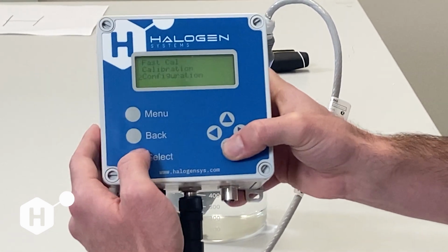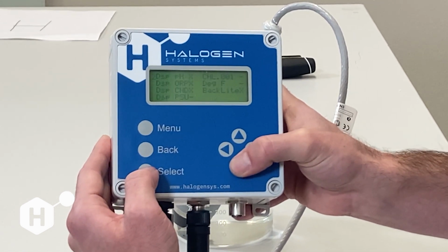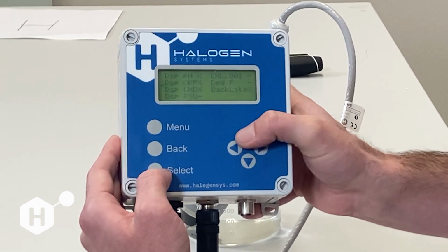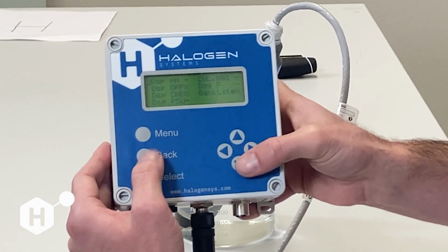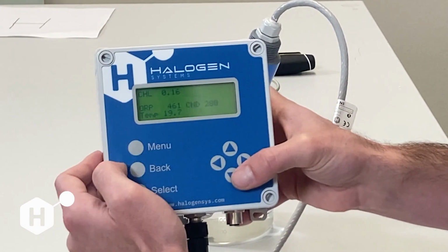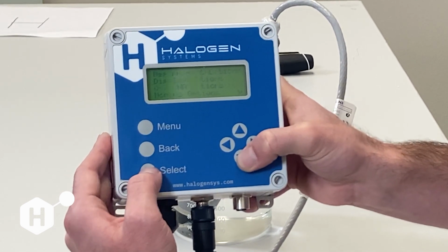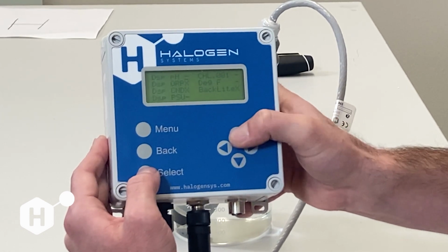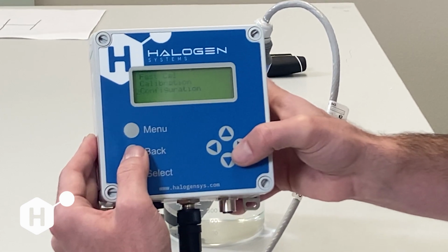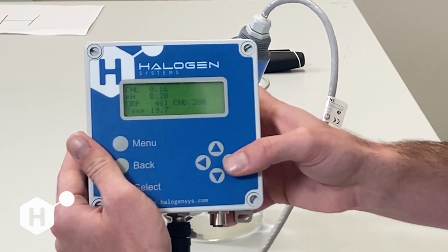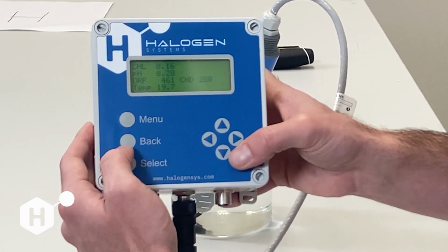I'll show a couple other things we can do. If we don't have, say, a pH sensor in here, and we don't need to see pH, then we go to Display Options and disable pH. Hit Select, and if we go back, notice how pH is missing. To get it back, same thing: Configuration, Display Options, and Display pH. And now we have it back. These are all good things to do the first time you power up the sensor, during your initial function test or initial configuration with the sensor in the system.